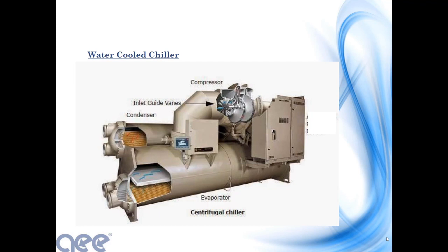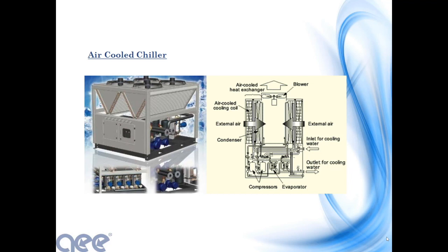So this section here is your compressor. When you talk about the different types of chillers, you're essentially talking about the different types of compressors. With all of these mechanical and electrical chillers, the evaporator chambers are generally the same, and your condenser chambers are generally the same basic technology. Where the differences are is with your compressor. How do you compress that refrigerant to get the different volume compression so that you increase this pressure and increase this temperature? And with an air-cooled chiller, it's all in one package.